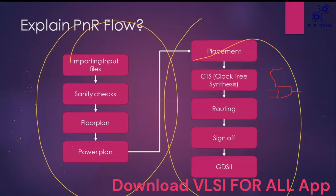I will explain the main inputs. The gate level netlist, which is synthesized by the synthesis engineer. We need that netlist. Next, the technology file. Next, the .lef file, library exchange format. These are very important files, along with tech files and SDC. In synthesis, I haven't mentioned another file, the .upf file. UPF means Unified Power Format.